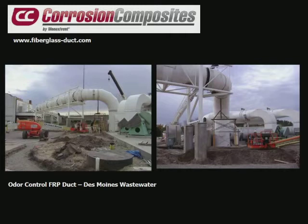The current method for treating odors around the wastewater plants is to use a biofilter. It's the most economical and green, earth-friendly way to do it. And the biofilters are large beds of bark or compost that they bring all of the fumes through, and they inoculate the bark with a sulfur-loving bacteria. And when the air flows through the beds, comes up under the bottom and flows through the bark beds, the bacteria eat the odors, and it's pretty efficient. But the problem is they have to have large volumes of air to do it.